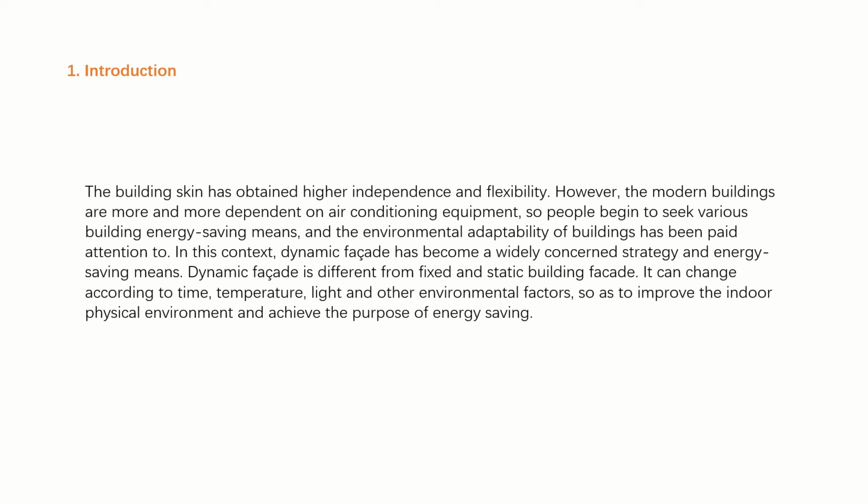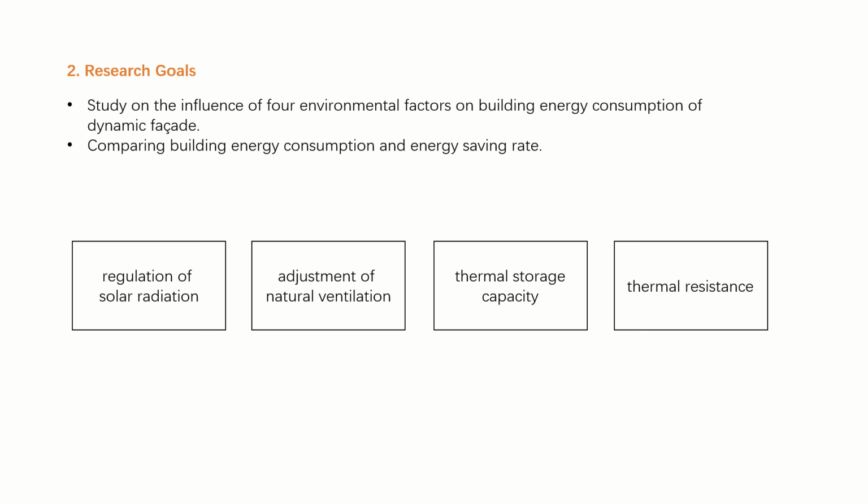However, current studies are mostly about the morphological changes of the dynamic facade. So, this paper extends the study to 4 environmental adjustment factors, including regulation of solar radiation, adjustment of ventilation, thermal storage capacity, and thermal resistance, to explore the advantages of dynamic facade in energy saving from the perspective of energy consumption.